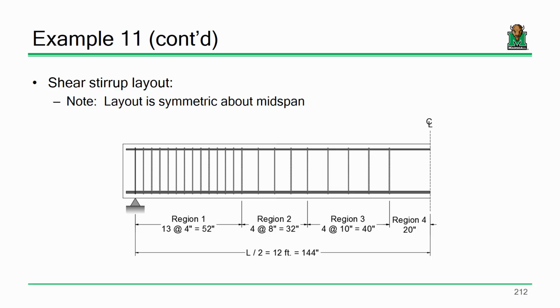That is common to have multiple regions, because if you can shave the number of stirrups in a given beam, you might go, well, what does it matter if you had 20 stirrups versus 18? Does that really affect the economy? Well, if they're using 800 of those beams in a given building, yeah, that does matter. This is a very important point to make.